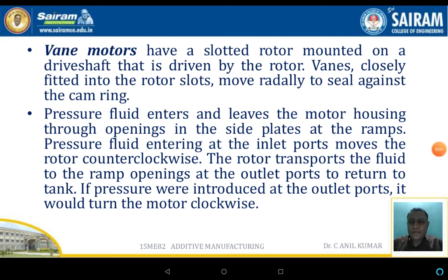Hello, welcome back for the next session in System Drives, Devices and Actuators. In this session, we will discuss vane motors, axial motors, bent axis motors, radial motors and the performance of hydraulic motors. Vane motors have a slotted rotor mounted on the driven shaft.